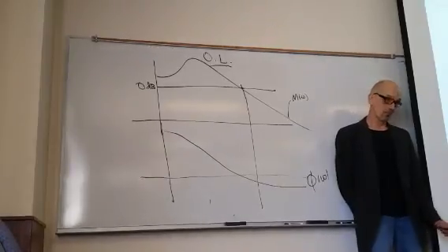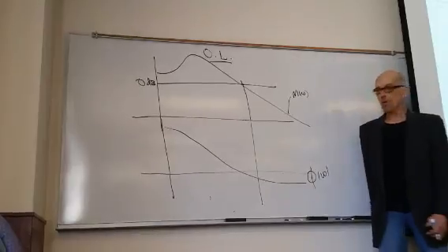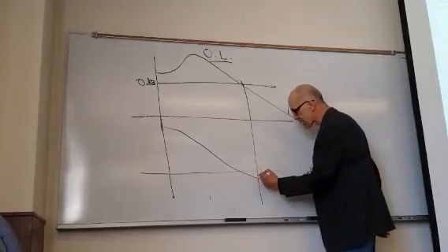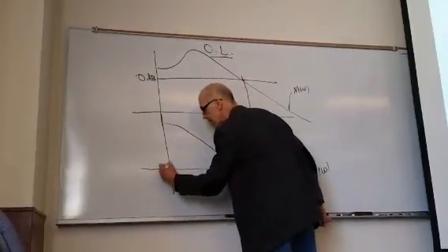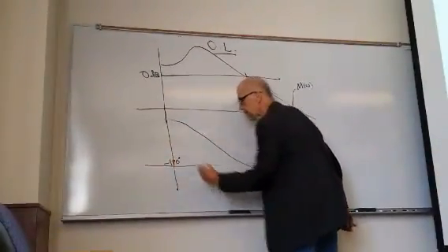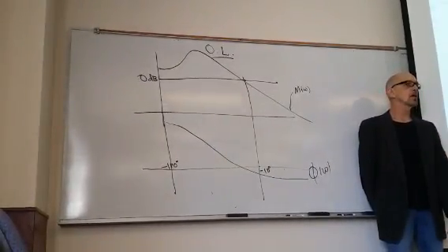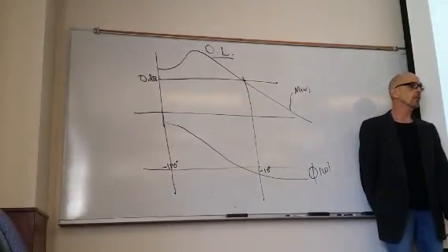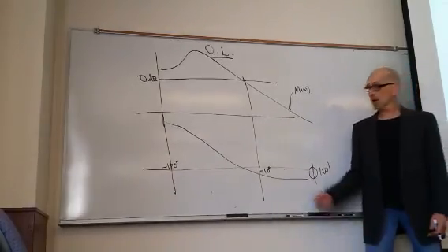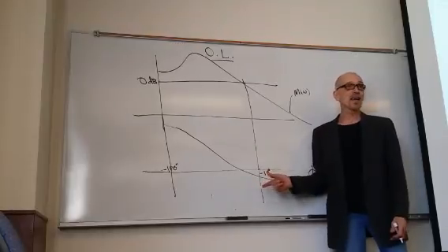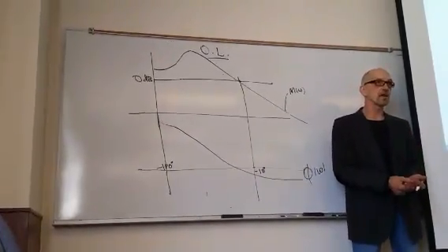Okay? So, all right, then what do we do? We get the phase margin. So suppose the phase margin is minus 10 degrees. So this is minus 180, right? Correct? All right, now let's suppose we want a phase margin of plus 30. So you say, well, my current phase margin is minus 10. I need plus 30. My compensator has to give me 40 degrees of phase.